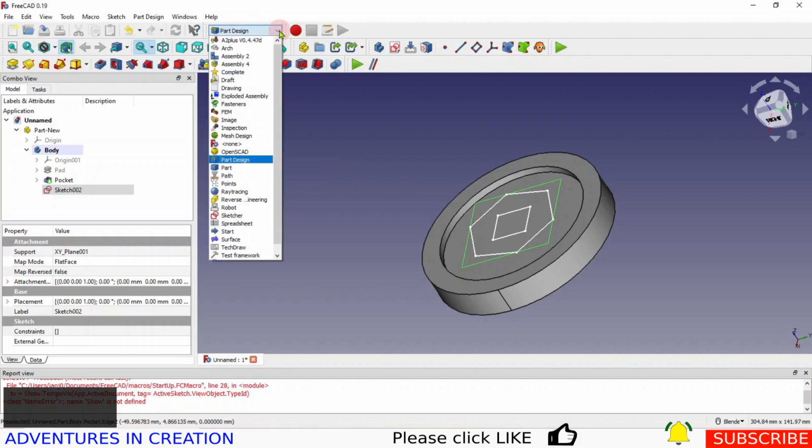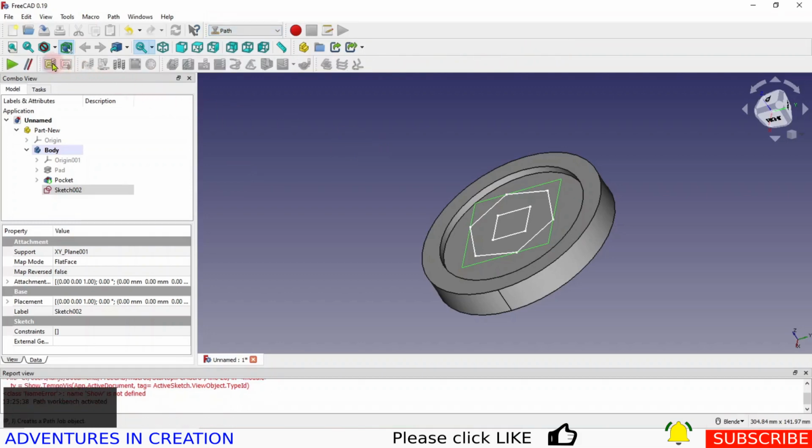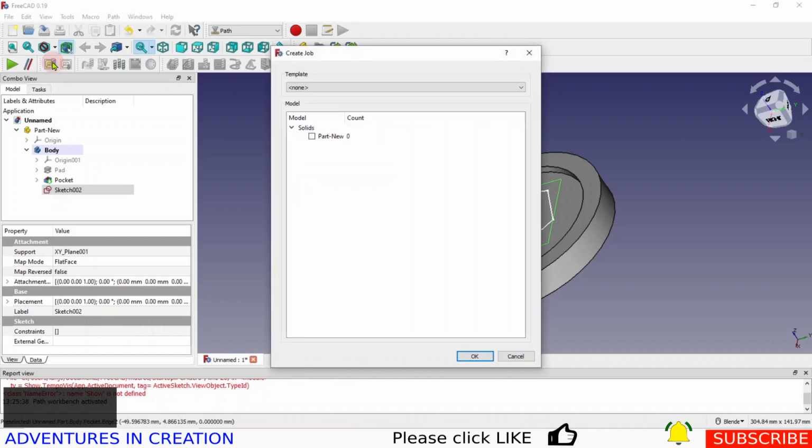First thing we want to do is switch to the path workbench, and once we're switched, we are going to start a new job. Now, one thing I wanted to show you is when I do this, I can only see that solid as an option to add into my job, and not the sketch, which is what I need for engraving. So we're going to change something.